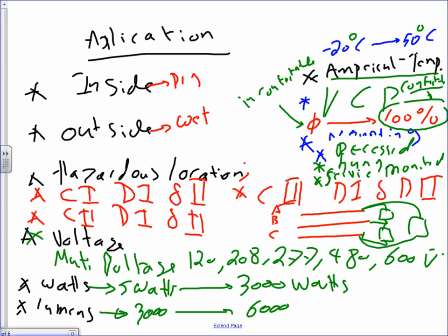So we move on from the voltage. I would say the best is to have multi-voltage because it matches any voltage you want. Now, how do we decide the voltage? By the way, which is the most common? The most common is you burn at 120 and you burn at 277. These are, I would say, 90% of the fixtures that you have. You're going to burn them at either 120, in our case, our project, or 277.